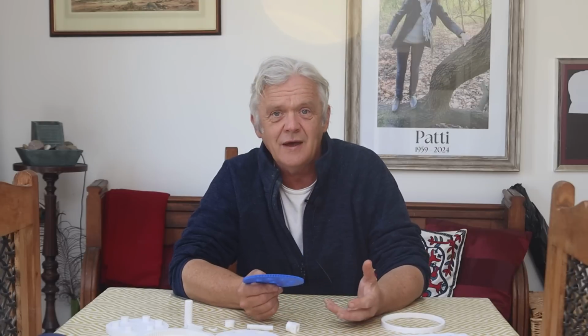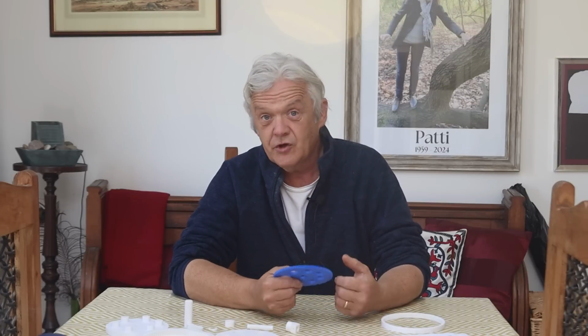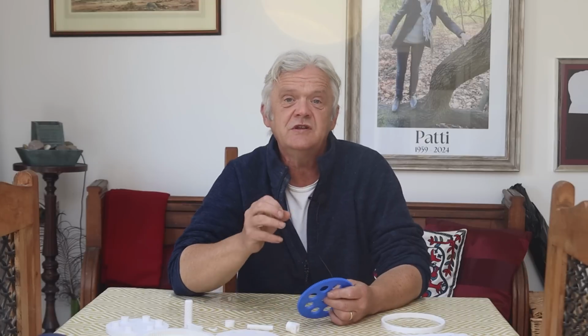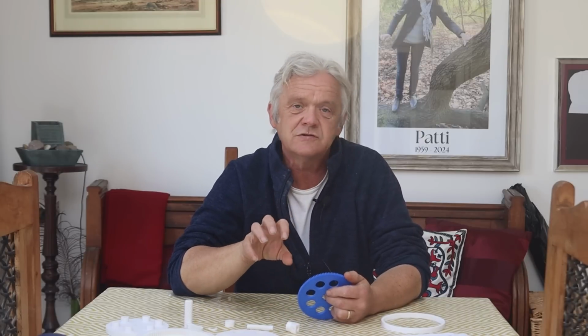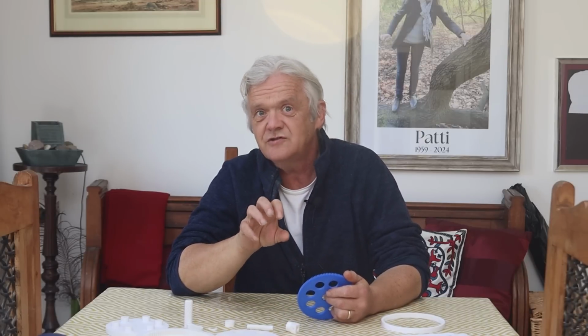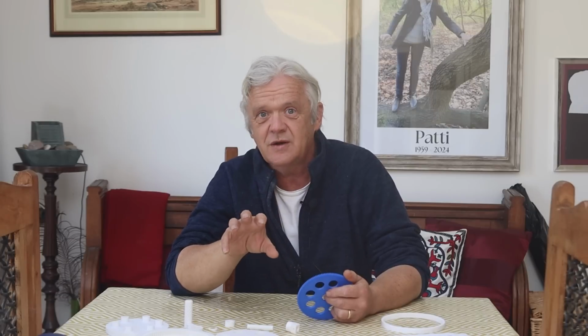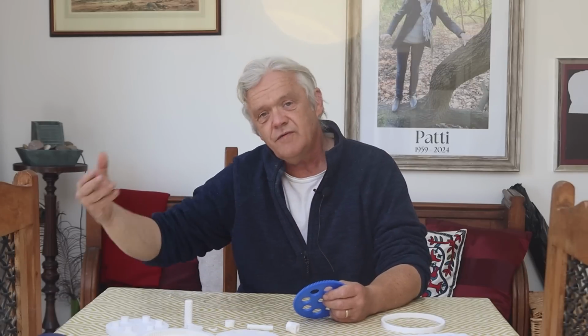A full description includes things like where is it located, how big is it, what kind of shape is it, and how does it relate to the other shapes. And those are the constraints. They're the things that you put in to describe that shape, its location and position, its size, and what kind of shape it is. So that later on, if you want to do those other things, they're easy to do because you've fully defined the shape.